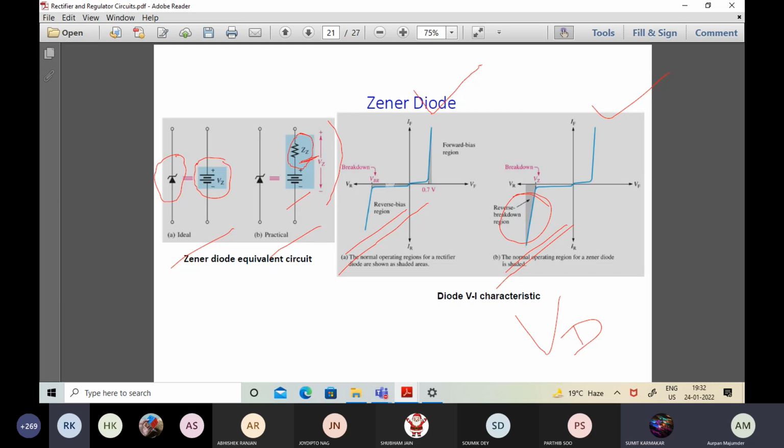In avalanche multiplication, the value of breakdown voltage is high. The current multiplication may be beyond the limit, owing to which the corresponding diode may burn out. So that is a very crucial factor. That was why, if you can recall, we talked about being very careful about the peak inverse voltage operation in rectifiers. It should not exceed the breakdown voltage, because once it exceeds the breakdown voltage, it leads to a condition where the diode gets burnt out.